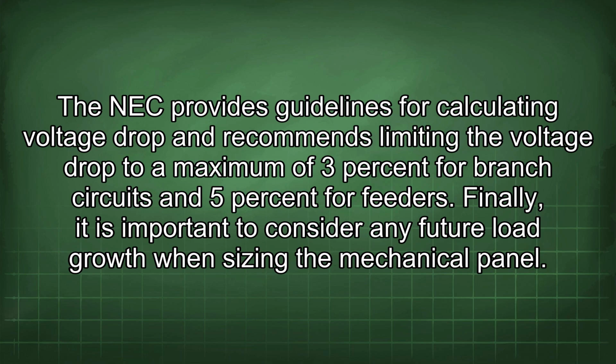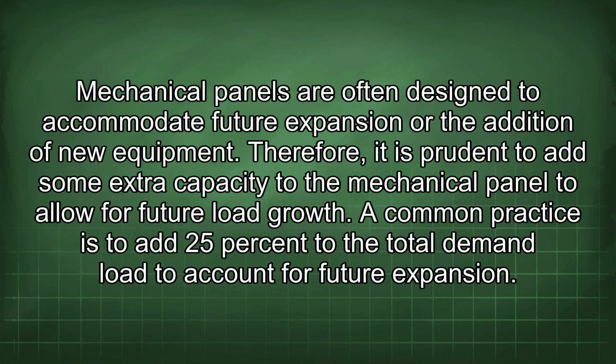Finally, it is important to consider any future load growth when sizing the mechanical panel. Mechanical panels are often designed to accommodate future expansion or the addition of new equipment. Therefore, it is prudent to add some extra capacity to the mechanical panel to allow for future load growth. A common practice is to add 25% to the total demand load to account for future expansion.